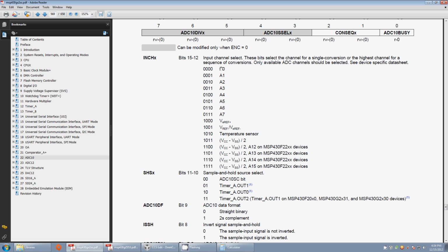So this ADC is going to finish this sample, and then instead of throwing an interrupt, it's going to tell the DTC that it's done, and the DTC is going to store this value in the first byte of our array. Then it's going to sample the next analog channel, and when it's done, it tells the DTC to store that byte in the next value of our array. It does this till it gets to the last value in our array. It's going to store the last sample value, and then after all that's done, we're going to get one interrupt request that says all of your data is done and it's been stored in this array.